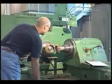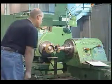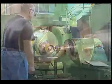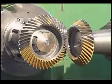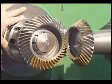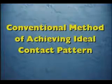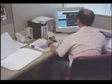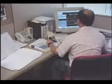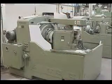The size and position of the contact pattern has always been a primary design consideration for gears, and for many years achieving a good contact pattern was performed through the same methods that the vast majority of gear producers still use today. The conventional method of achieving an ideal contact pattern is performed in this way. First, an engineer will make an educated guess at how the gear should be made so that the contact pattern will be correct. Next, the part is fabricated and the gear teeth are machined.